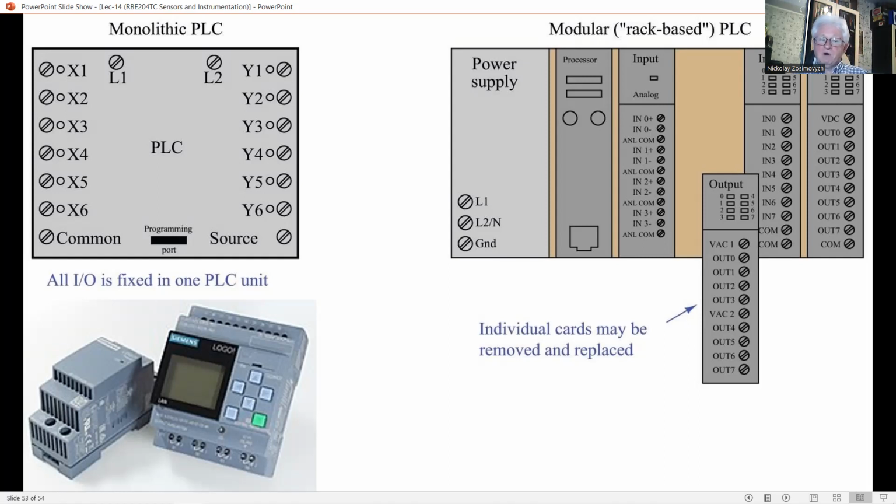The capabilities of a PLC can be determined by such parameters as the number of input devices, usually divisible by 16, and the number of output devices, like 12, the number of program steps it can handle, like 2000, and the speed at which a program can be executed, how many steps per second, for example.